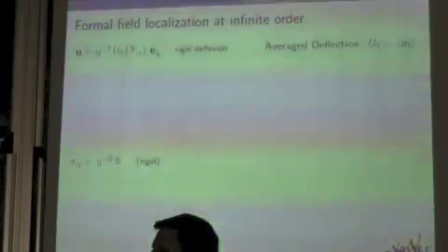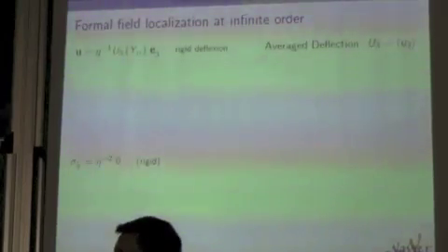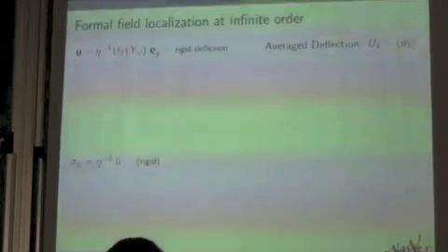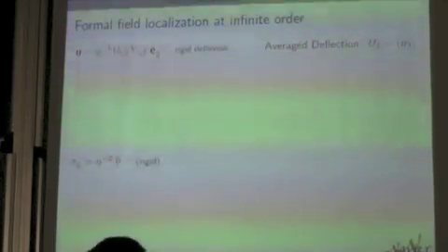So I will, this is formal, I will just show you how things are going, and this just gives you the overall picture of the result. So if you go at the first, most leading order, what you get as solution for the displacement is just a vertical displacement. This vertical displacement is actually the average of the full displacement of the plate through the thickness.